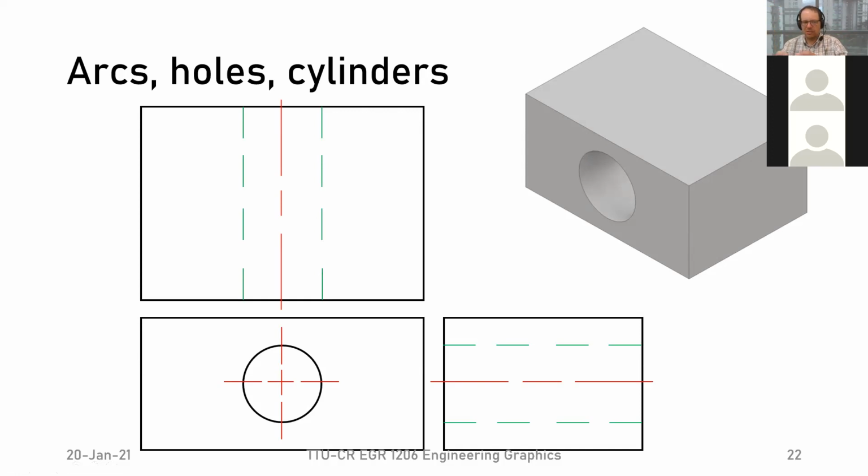If you think about a cylinder, if you look at the cylinder from the side, then it looks like a box. And this is what we see. And then we also have to add the center line, right? The hidden lines don't represent something that has straight lines but is a circle, so we have to have our center line that goes exactly along the center line of the cylinder. And of course, if we look from the right hand side, then we do the same thing, right?